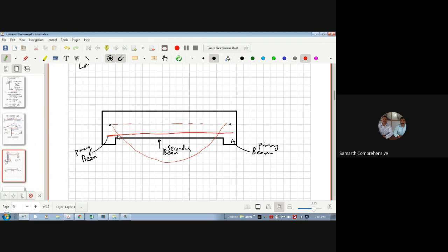So as there is a tension, I need to transfer this tension here or not. अभी ये थोड़ा question है tricky. So here you can transfer this. Correct? So the development length will be from here to here. Are you getting? Because this bar is in tension. There is a tension here, which will be transferred here. Right? Getting? Yes, sir.